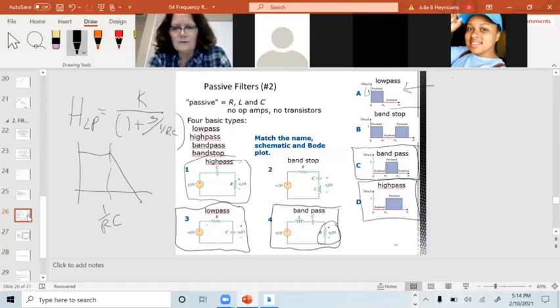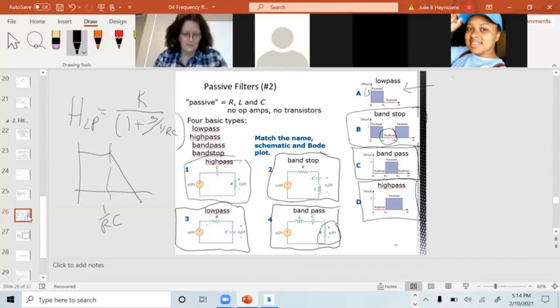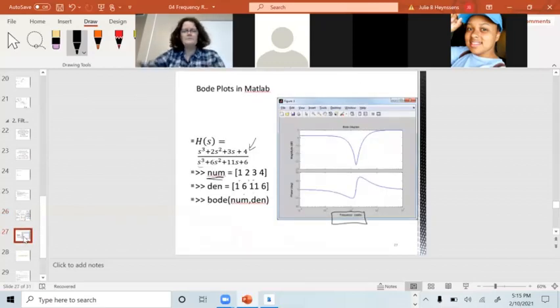To get a band stop, it filters out some noise that I have, like the radio station transmitter next door. All I do is I swap the position of the LC and R. I take the output off of the LC combination, and I'm almost done. I am done. Knowing about these filter characteristics might help you. We'll talk about that later.